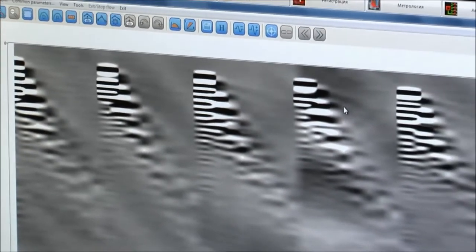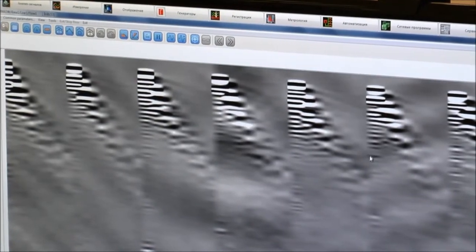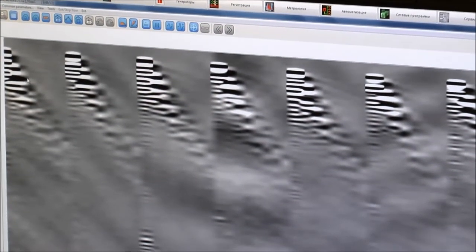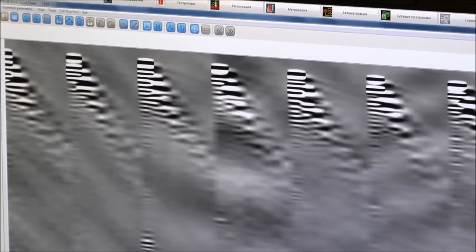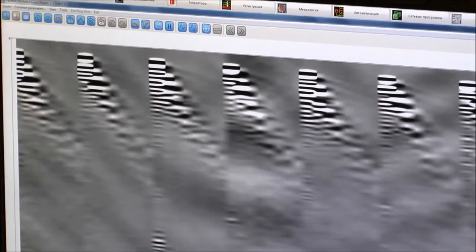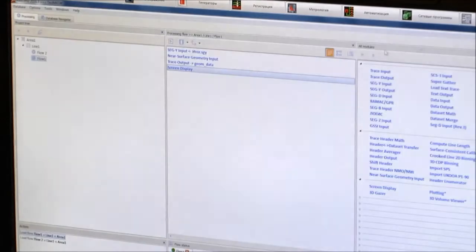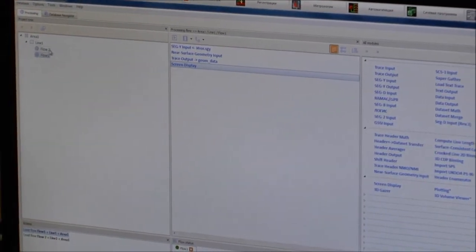So what we can see now is quite similar to the diagram from ZETLAB SEGY-file view program. Here we can see data from 7 shot points, having 8 channels each. The seismic wave achieves each consecutive geophone with certain delay. As this flow has already prepared the data we need for MASW analysis.